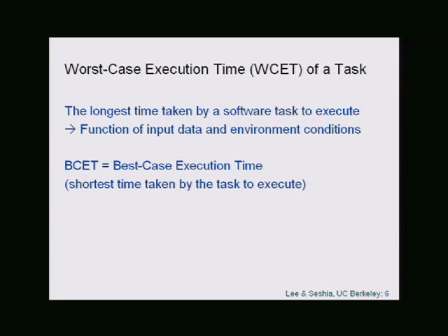Yeah, Rafael? Yep, so it depends on the software environment. Other threads running, the OS scheduling policy, interrupts, right? The hardware target, absolutely. If you run the program on different processors, you'd expect to see different execution times that depend not only on the clock speed, but also on the specific characteristics of the processor. So the details of the pipeline, the details of the cache, the memory hierarchy, okay? So there's a whole bunch of things in the platform that it depends on.